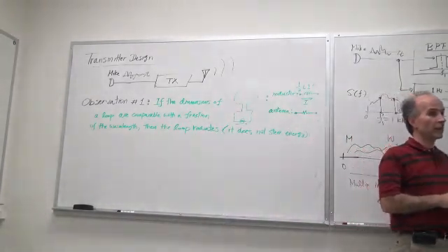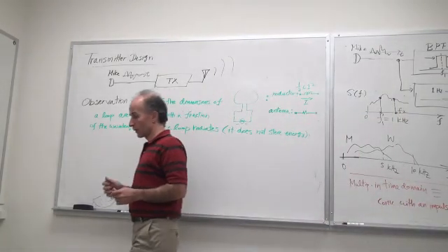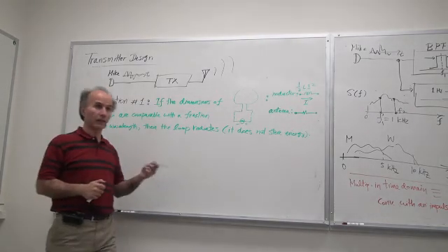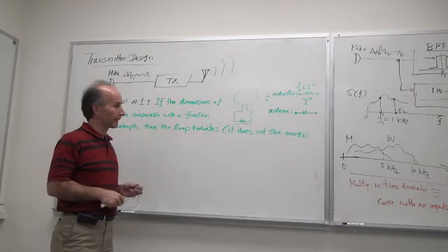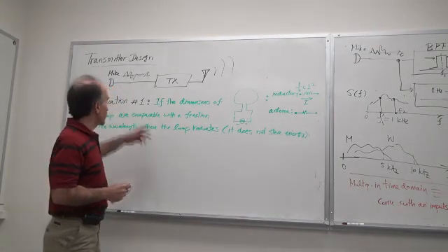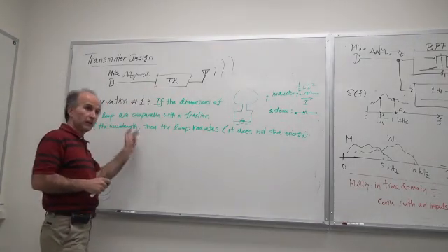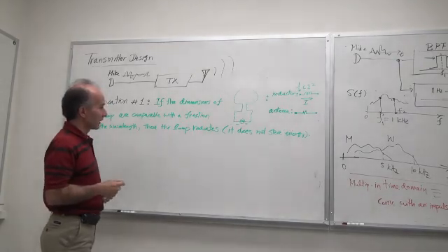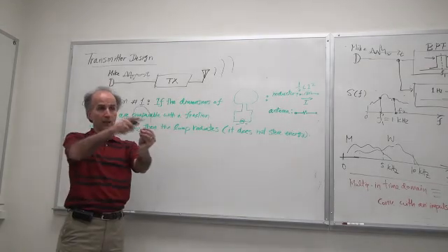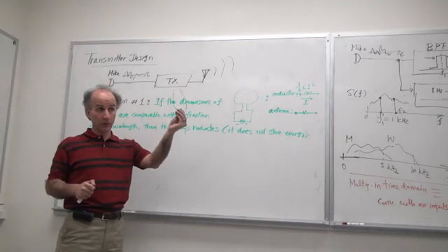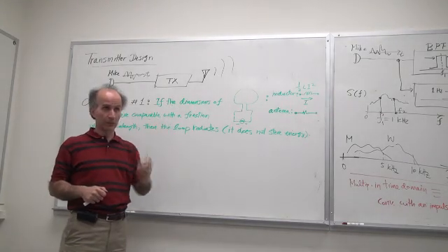Okay, so that's the key concept in antenna design and in general in how you look at a circuit component and decide whether that can be a nice little inductor or it can be something more complex like an antenna. All right? Okay, but this observation actually dictates the design of a transmitter in a slightly different way. So what I said was, to build a good antenna, I have to pick the dimensions of the antenna, like diameter or something, right, to be comparable to the wavelength or fractional wavelength, maybe lambda over 4, lambda over 2 or something. All right, okay.